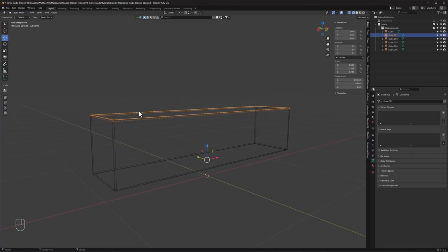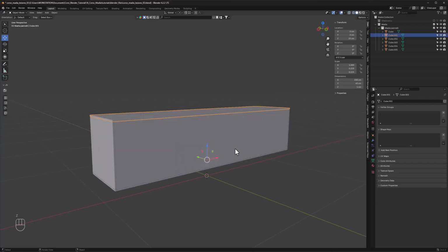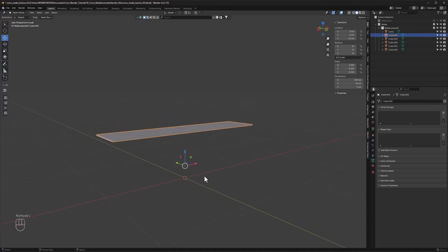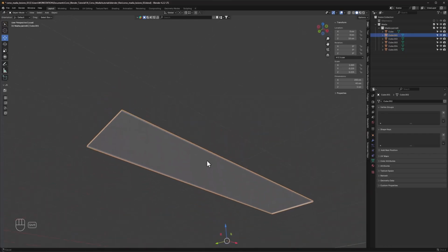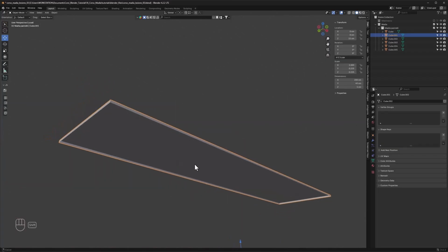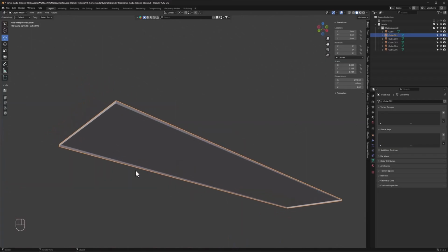Select the top panel of the mesh and set the view to solid. Press the slash key on the numeric keypad to isolate its geometry, temporarily hiding the other parts of the model. To better see what is missing from the selected model, we need to position the view underneath the panel. It is clearly noticeable that the bottom face is completely missing. Let's see how to proceed to properly close this part.